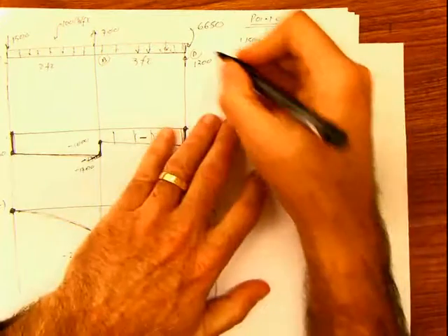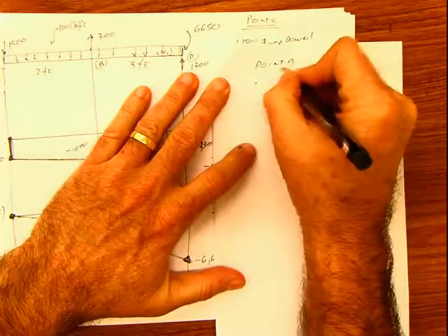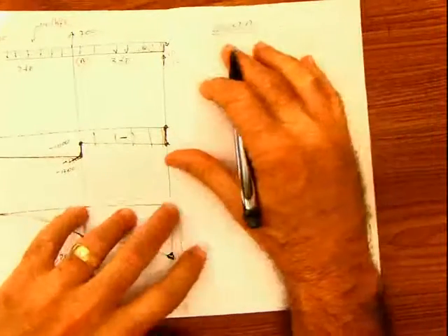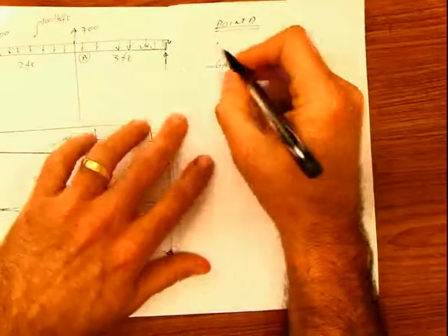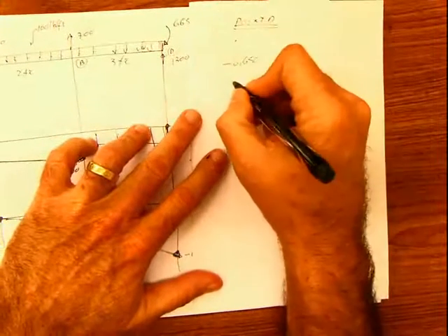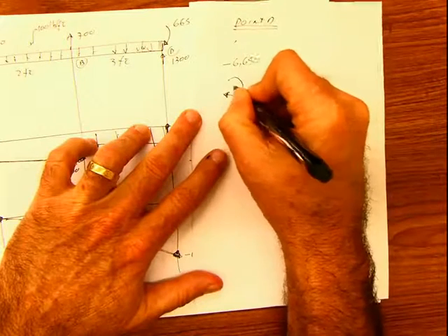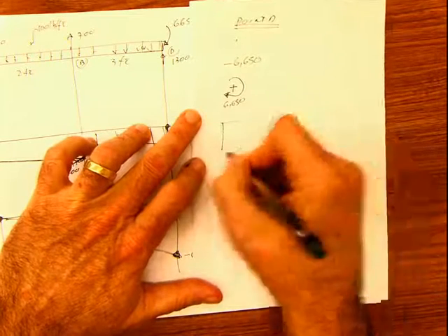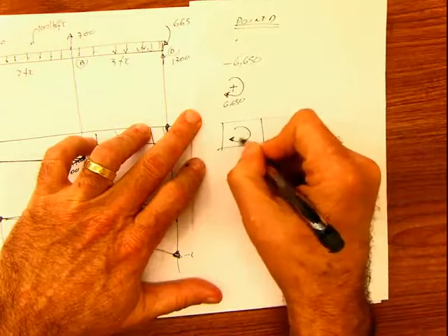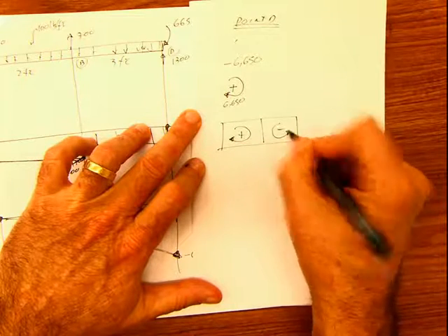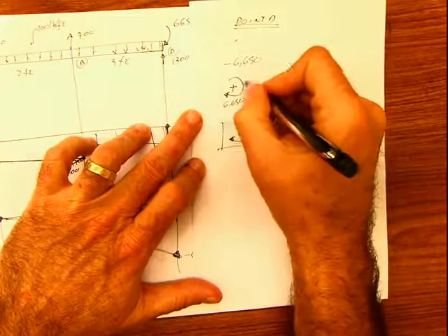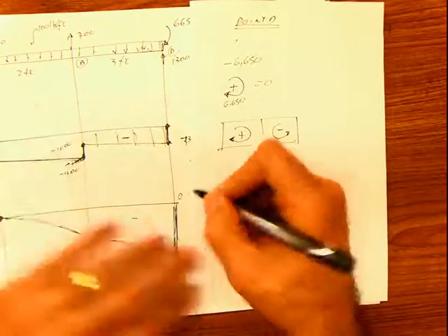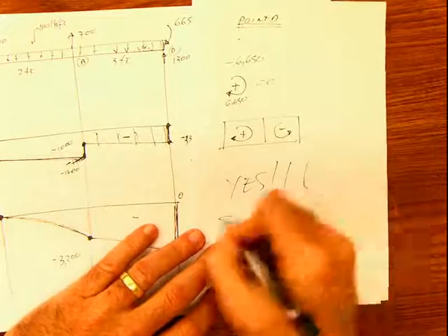At the point D, we find a force. Well, first I have negative 6,650. But then I find this concentrated moment, and the concentrated moment is acting in this direction. That means that it's positive. Remember, once again, I'm going to write it again: for concentrated moment, positive. For concentrated moment, negative. This is positive. This, negative. Plus this, positive is 0. That means this jumps to 0, and you say yes. Okay.